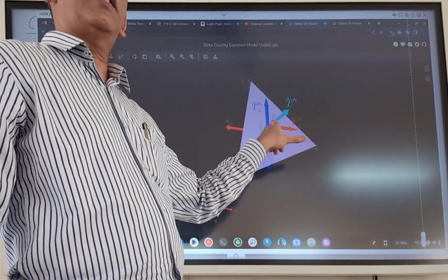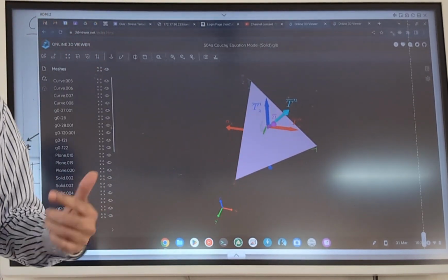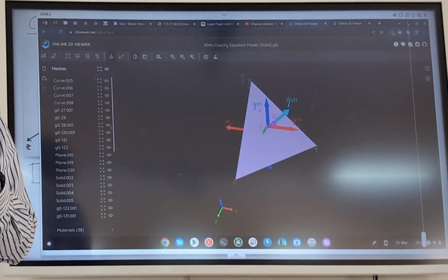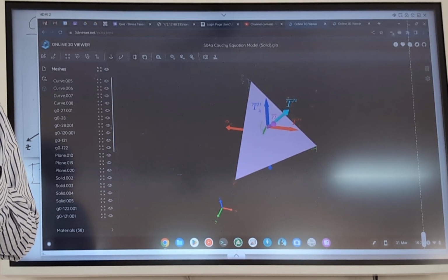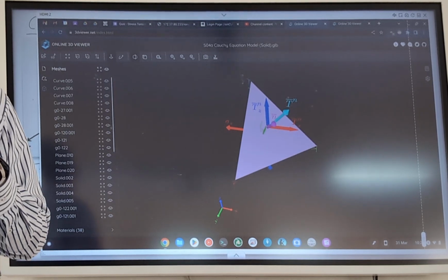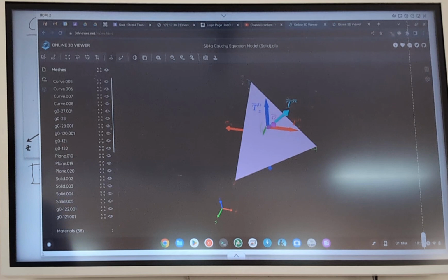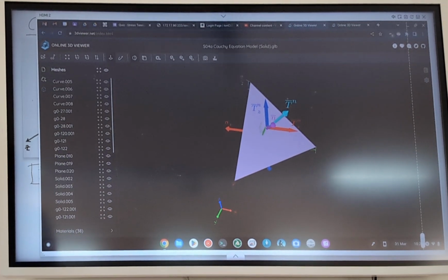So if you note the traction vector along the x axis, can you tell how you calculate force from the traction vector? What is the definition of traction? So traction is a ratio. So it is a ratio of what by what? Force upon area. It is just like what you learned in strength of materials about stress.